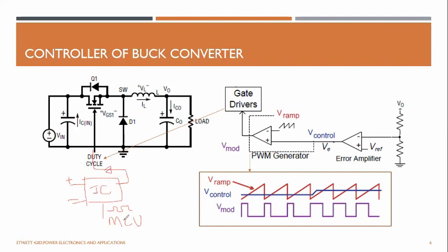The thing is, Arduinos and such can only provide 40 milliamps of output current, very low. You can simply run an LED, right? But for this kind of power switch driving, you need currents from 1 amp to 4 amps. So you provide this voltage signal coming from the Arduino, and the gate driver amplifies it to drive large current pulses at the same frequency. That's why you need a gate driver to drive this.